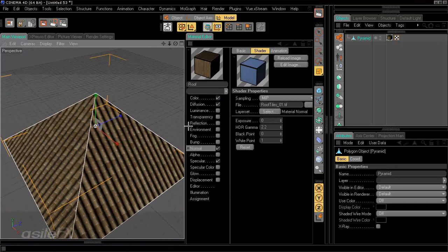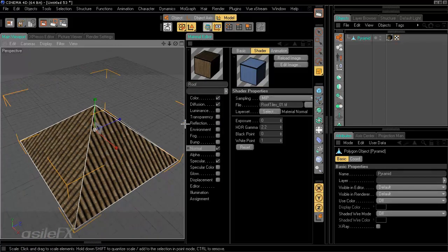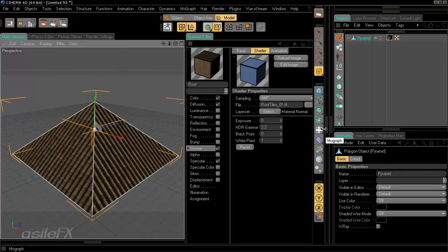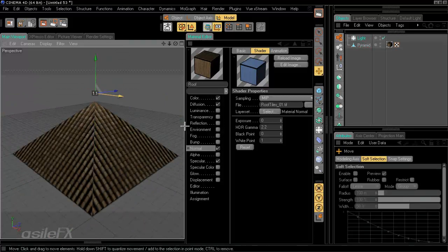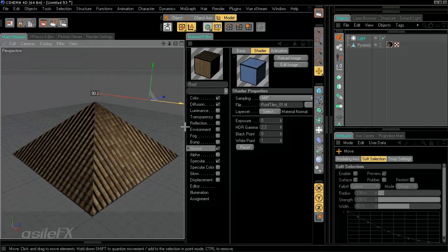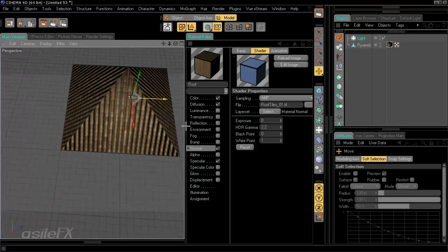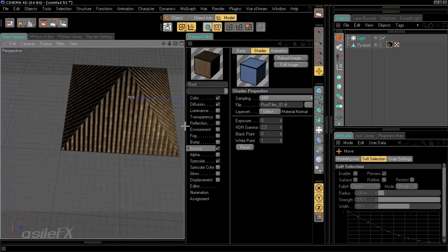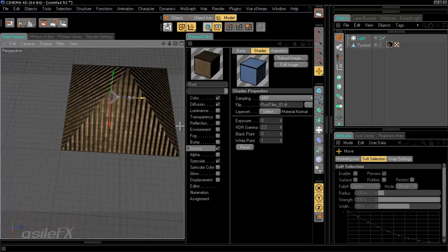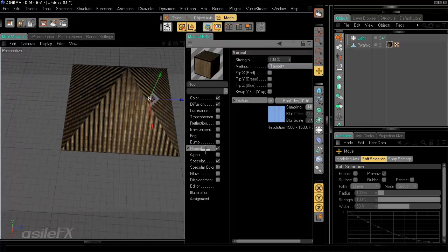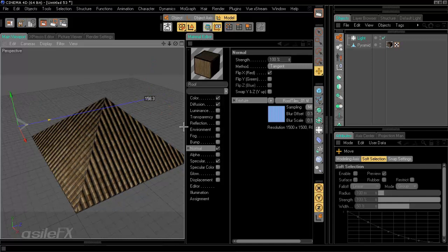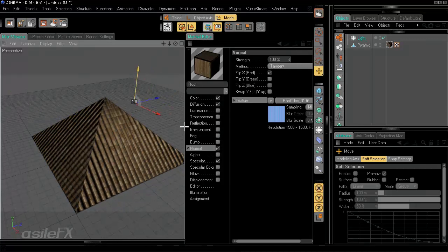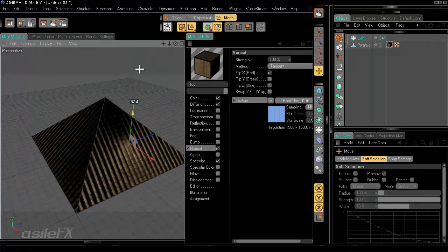And then we also want to have something better to judge the lighting. So we may need to flip around some of the texture channels. It looks like the red needs to be switched. So we go to the normal, flip around the red, and just check the Y.